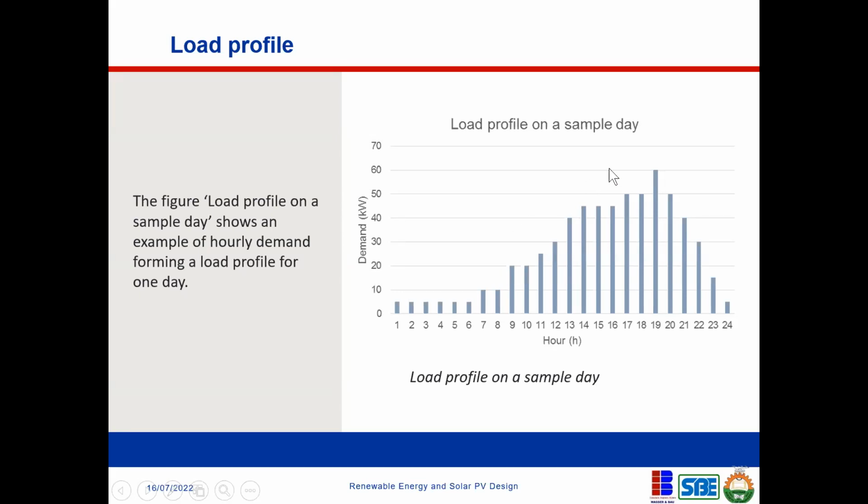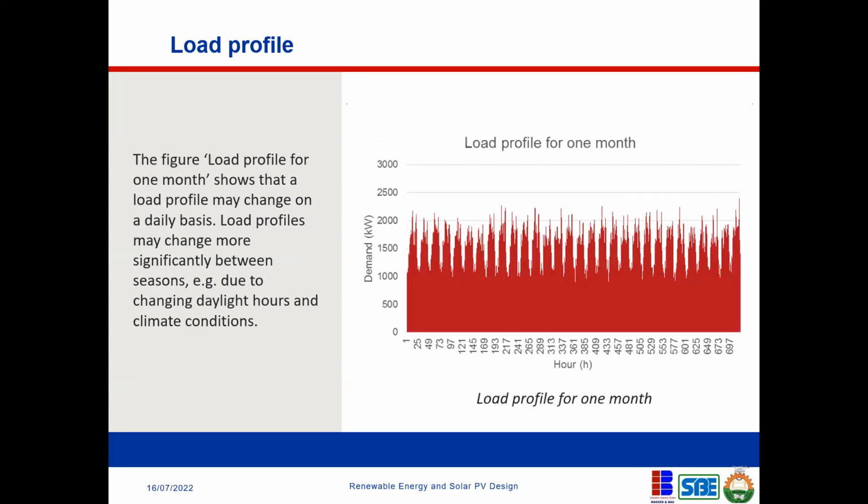If, for example, it's a washing machine, this is a load that you can do at any time. It is work that you can do at any other time apart from this period. So you can advise the customer, please, can you do your laundry at 9 a.m. instead of doing it at 7 p.m.? Do it at 9 a.m. so that you can have a lower capex to do your project. So this is why a load profile is important, to establish your peak load.